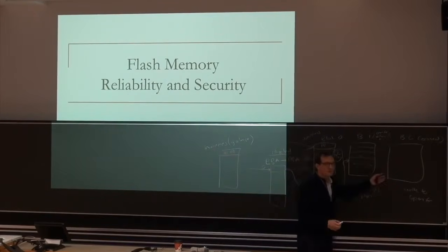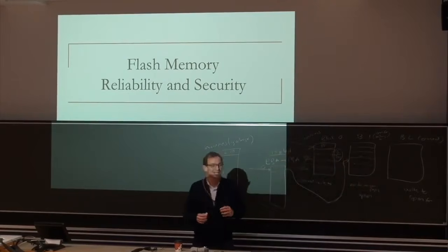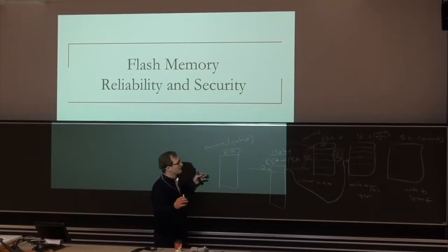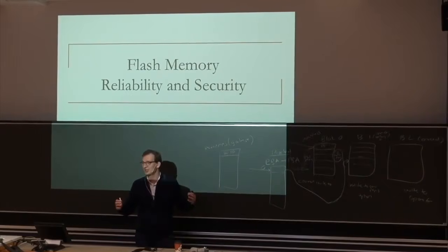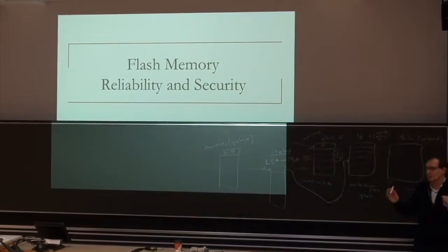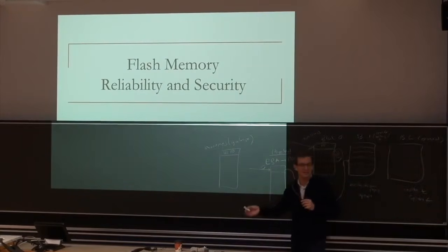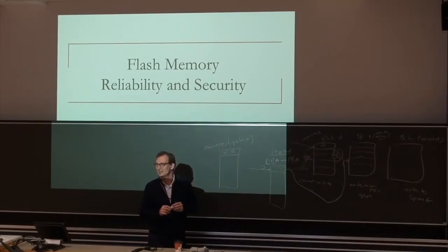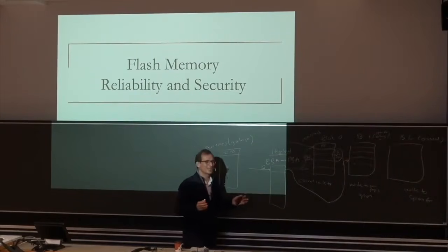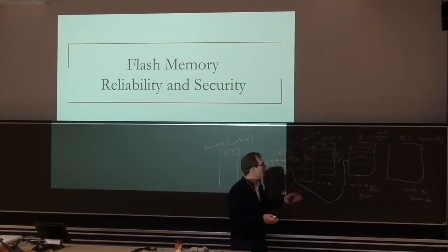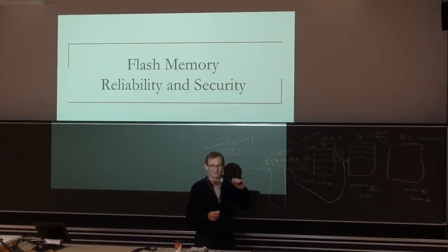So of course, to be able to do that, usually the space in flash drives is over-provisioned, meaning that they actually have more blocks than advertised to the customer, so that they can handle these sorts of moves more efficiently. Of course, over-provisioning is not good in general. Ideally, you don't want any over-provisioning because that costs, right? You would like to minimize the over-provisioning, but over-provisioning happens naturally because you want to handle these cases.